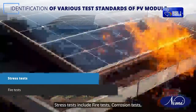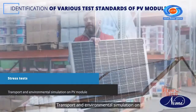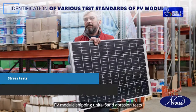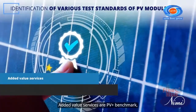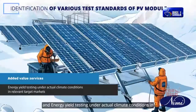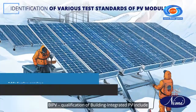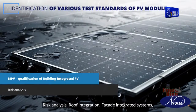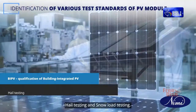Stress tests include fire tests, corrosion tests, outdoor long-term tests in different climate zones, transport and environmental simulation on PV module shipping units, sand abrasion tests, and snow load testing. Added value services are PV plus benchmark, qualification plus certification, and energy yield testing under actual climate conditions in relevant target markets. BIPV qualification of building integrated PV includes risk analysis, roof integration, facade integrated systems, hail testing, and snow load testing.